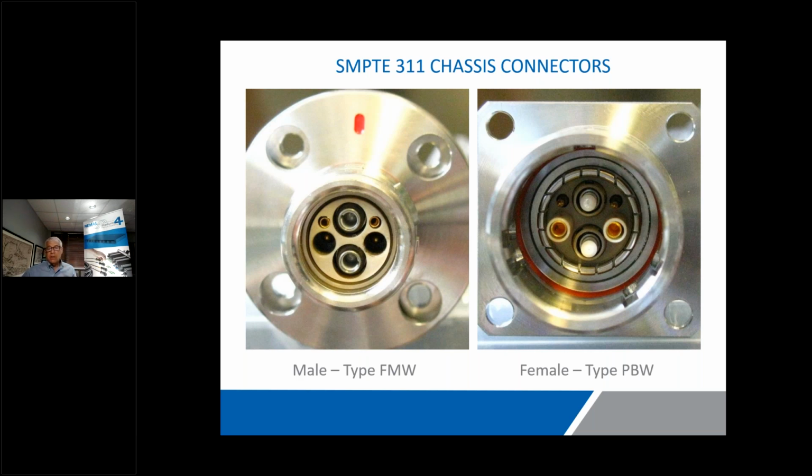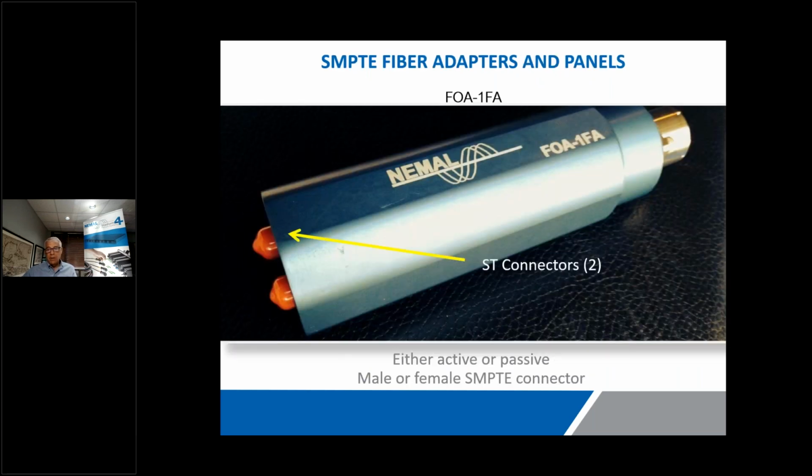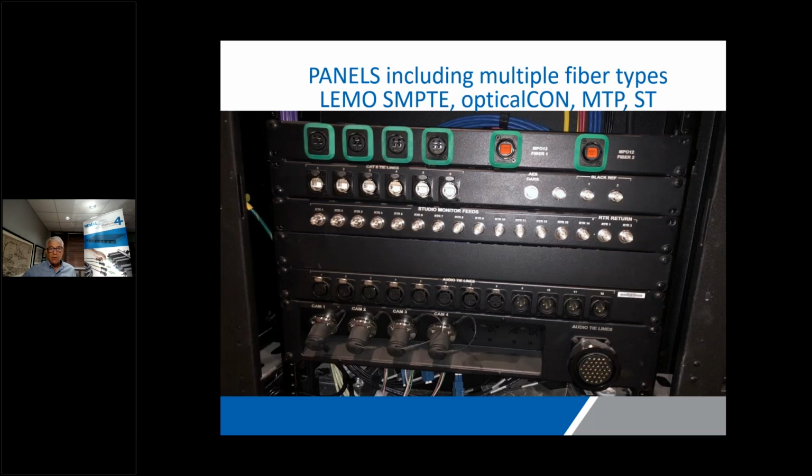The ferrule in these connectors is 2 millimeters, so it's not the same as any one of the standard. Then again, we are going to need separate cleaning and testing equipment to adapt to a 2 millimeter ferrule. If you need the SMPTE connectors and you don't have any SMPTE connector cables, you can use adapters that'll terminate these into STs or any other type of connector you use.